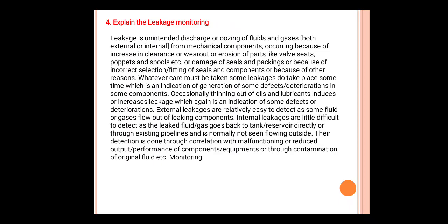Leakage is unintended discharge of fluids, and gases are also to be considered. That is called leakage monitoring. It may come from external or internal damage to mechanical components, occurring because of an increase in clearance, or wear out or erosion of parts like valves, seals, poppets and spools. Because of damage to these kinds of parts, some internal or external leakages may be formed.